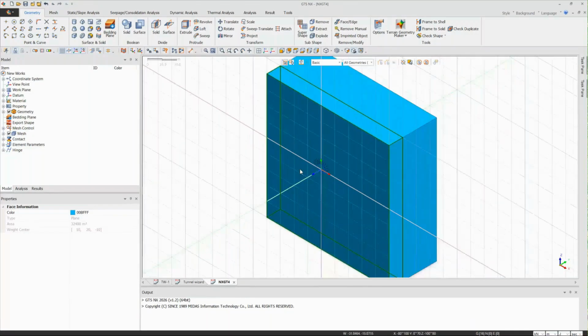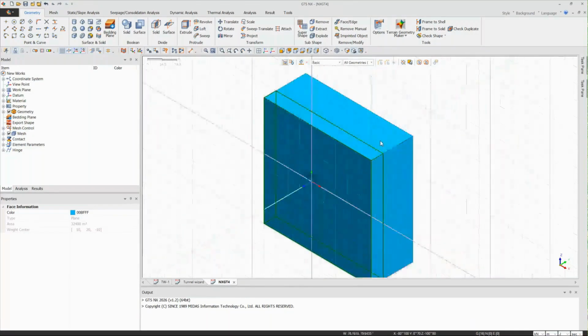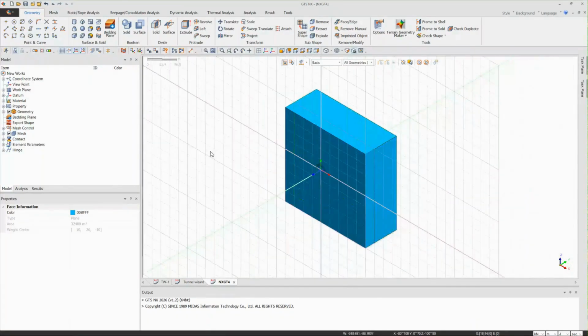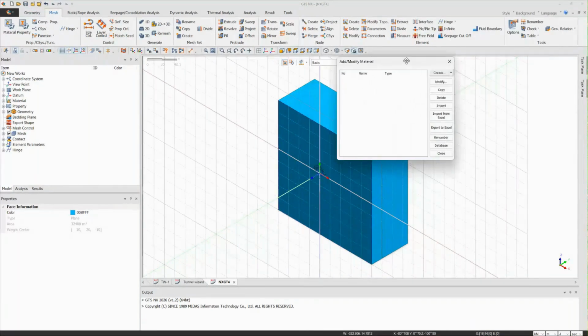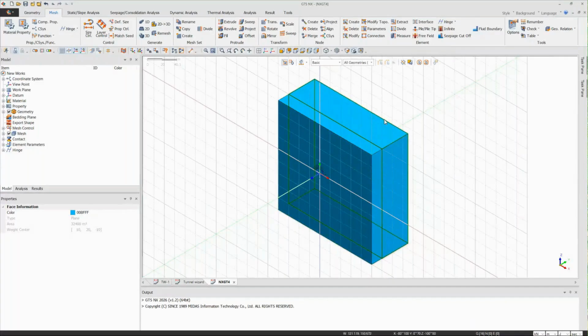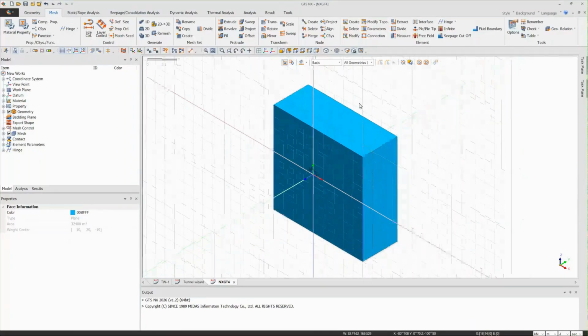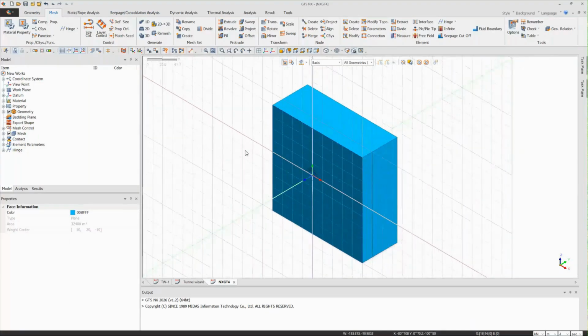I can extrude it, and then I just need to mesh the domain as per my material properties. I need to assign the suitable material properties to the meshing in those sections. And then for the assignment of the construction stages, I have some automation in the manual approach as well.